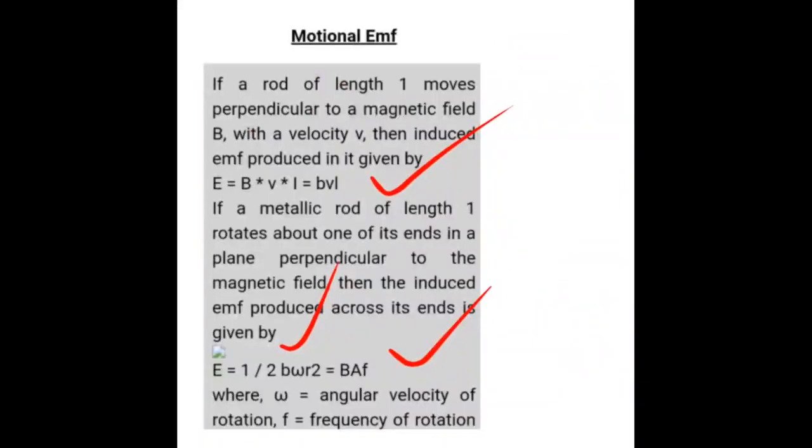Or we can say, if we differentiate both sides with respect to dt, here also we will get dt, right? Now d phi by dt is called EMF. So change in magnetic flux is called EMF here. So we will get N E equals L di by dt, right? L di by dt. So if you cross multiply, you will get the EMF. If the number of turns of the coil is 1, then we can say that E equals minus L di by dt.